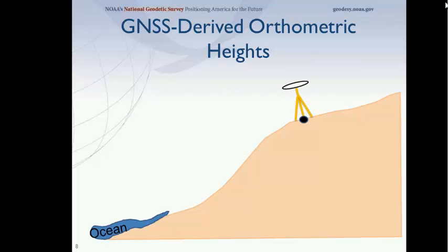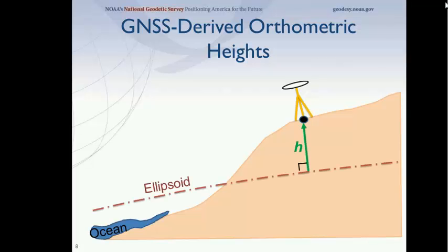next, and then take a GNSS observation or conduct a session, next, and what that will return is an ellipsoid height, some height normal to the reference ellipsoid, so you can get an ellipsoid height directly from your GNSS observation. And then at the latitude and longitude of that station, you can look up a geoid height from a geoid model. So you click next 2 more times.